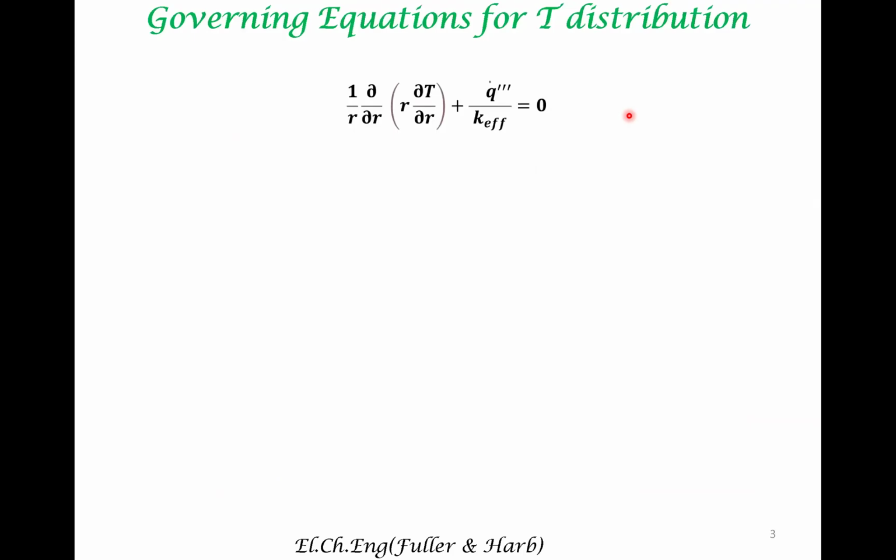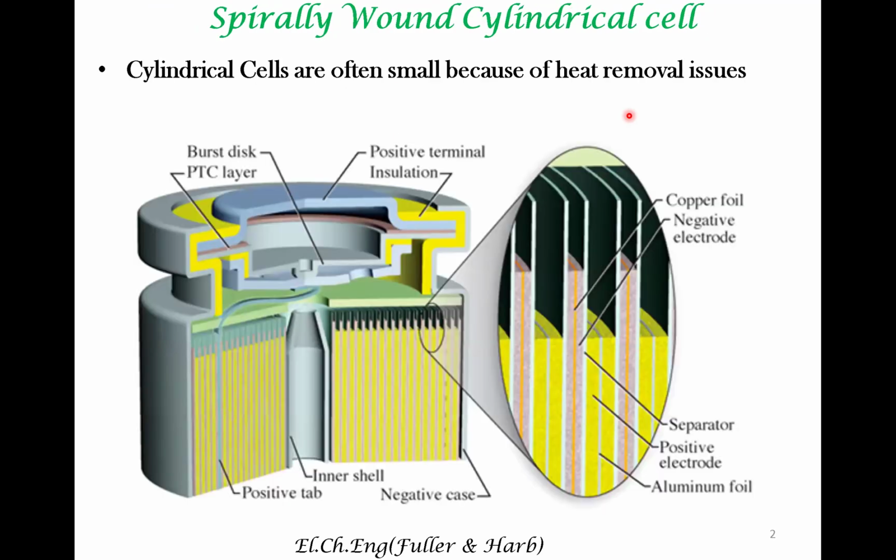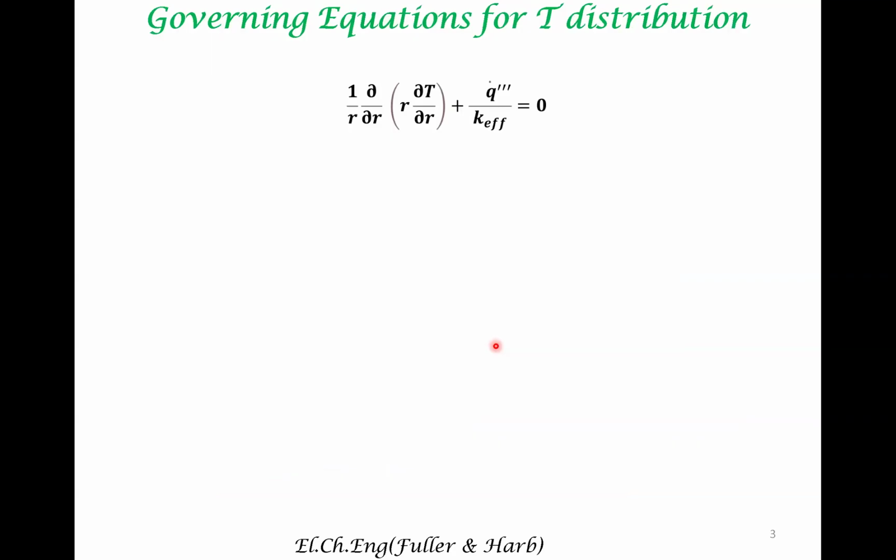So how to think about heat transfer in this system, you must have learned it in your heat transfer class, all chemical and mechanical engineering students especially. So heat is generated in the bulk of the system. It is conducted away, heat flux is conducted away, and heat is removed by convection from the surface of the battery, right? So the way to model this is via a simple 1D conduction equation.